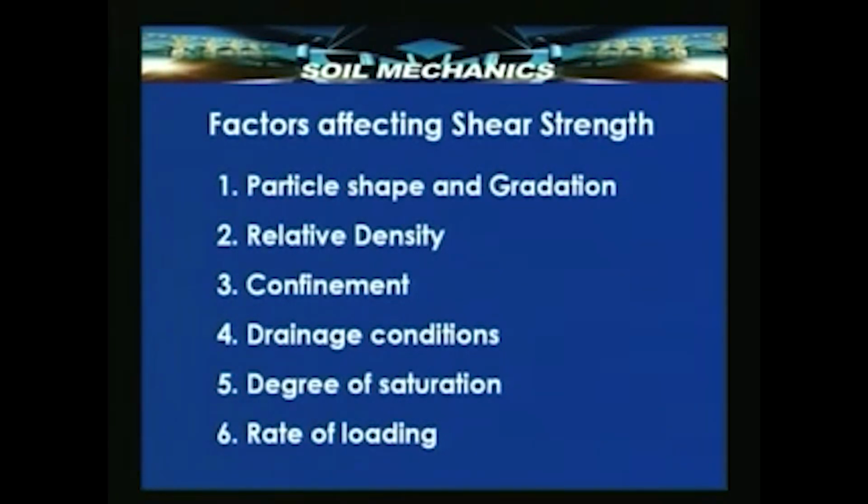Now, there are a number of factors other than this drainage which affect the shear strength of a soil. Primarily, we can identify 6 such factors. These 6 factors are listed in front of you here. The type of the particles is responsible for the kind of shear resistance that can be mobilized between the particles when they experience the interlocking pressure or the intergranular stresses.